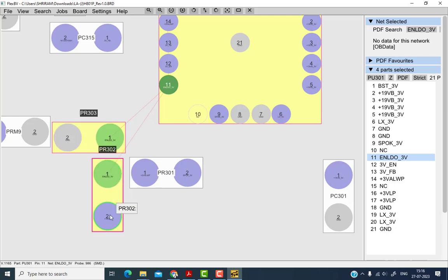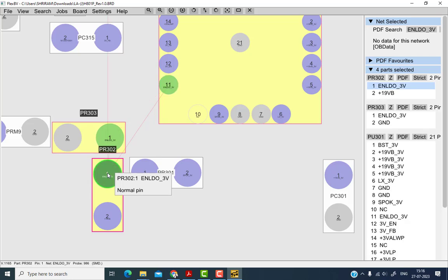Okay. Now, in this way, if the 3 volt is coming, check whether the 3 volt is not coming here at pin number 16 and 17. Here is a resistor in series, on 16 and 17. This resistor may be open. Voltage is going to the different parts. So this resistor is going to the different parts, so you have to check that.